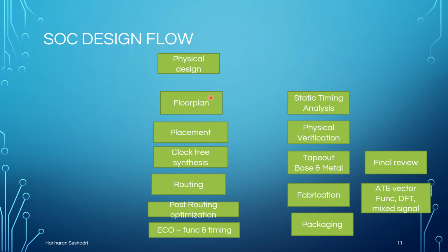That's the example. What block goes where? Where does the memory go? Where does the PLL sit? Where does the standard cell logic sit? Gates and flip-flops. That's a floor plan, right? Then the placement. Once you design a floor plan, how the logic is placed, that's called placement, right?